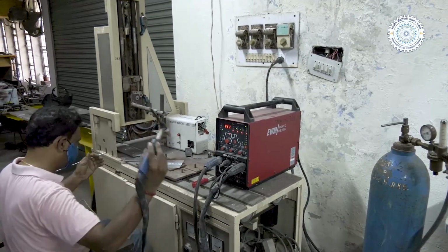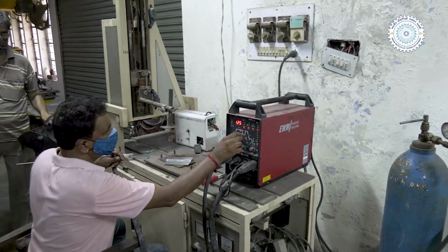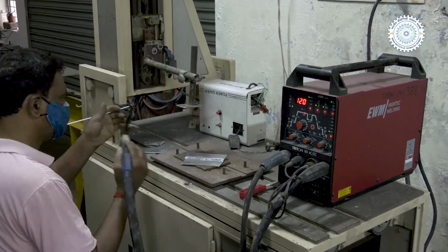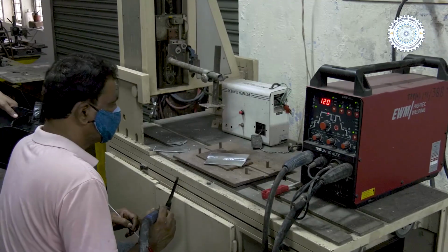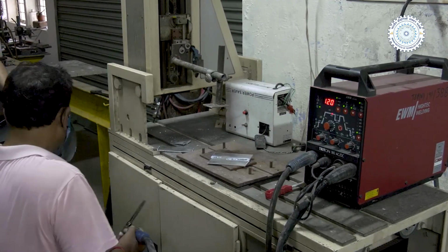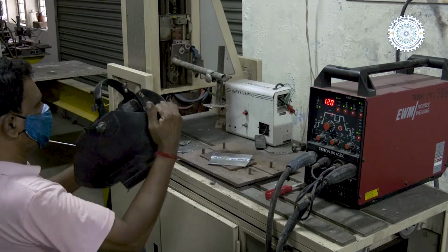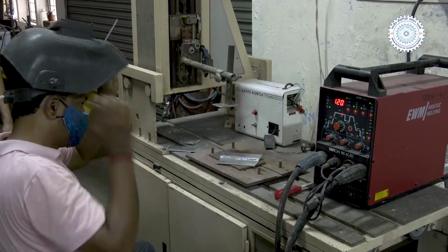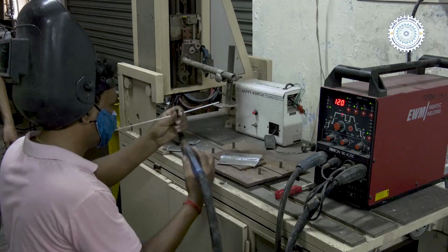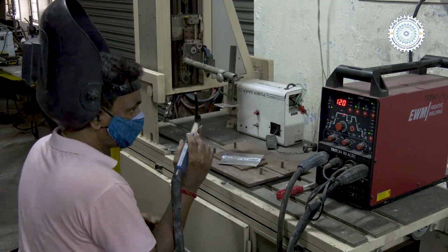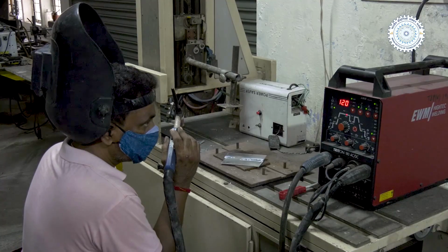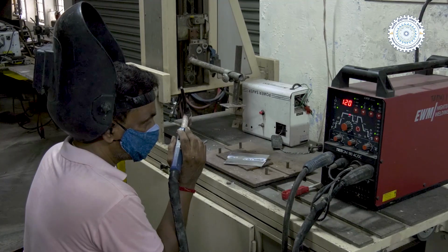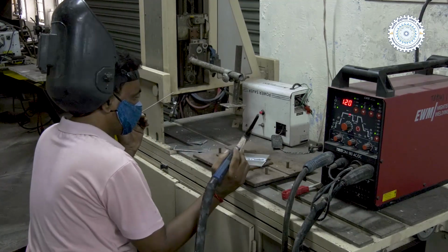After setting the welding current and ensuring the proper supply of argon gas, we choose the suitable type of welding current. Since this is aluminum, we will be using AC, and considering the sheet thickness, the current has been set at 120 ampere for the constant current setting. Okay. Now we will see how we start. We start the arc, and then using the filler the bead will be deposited using the GTAW process.